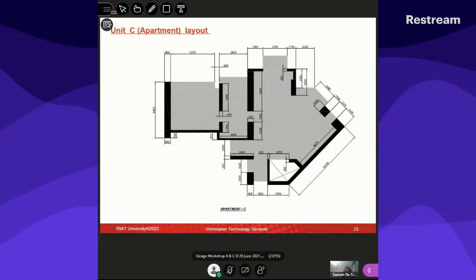But I will give you another alternative before I go from here. Go back again. One other option available to you is this slab. I use blue color here, as I originally suggested, one-way spanning slabs. Of course, you will have that yellow color situation here exactly the same. So you can go one-way spanning slabs, but this part is a little bit dodgy.